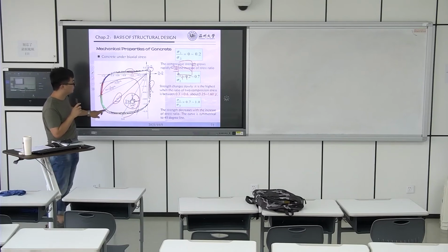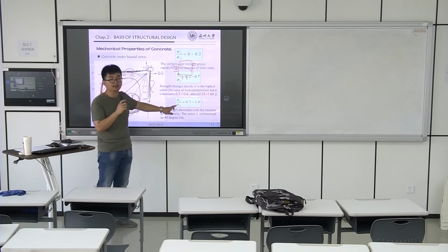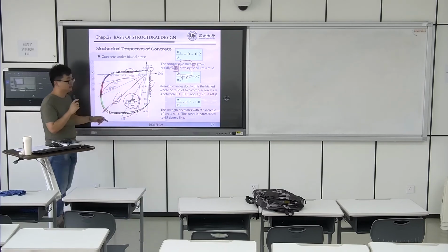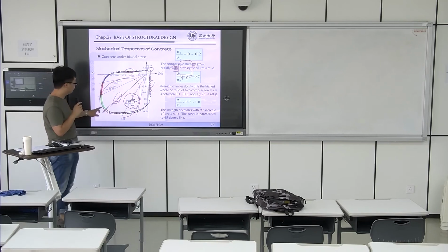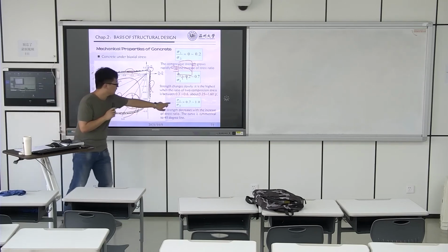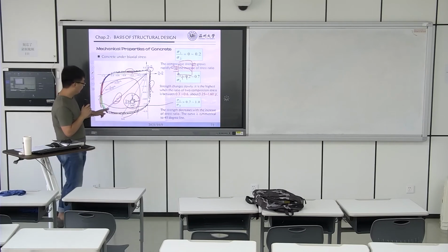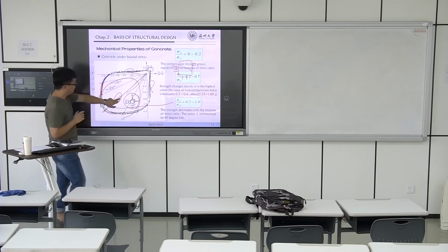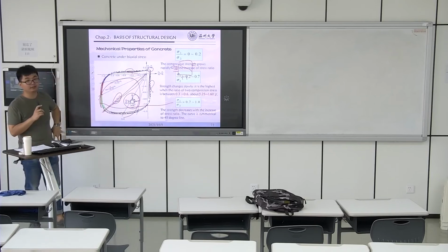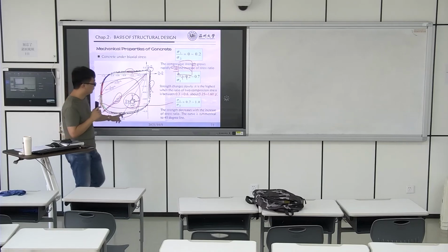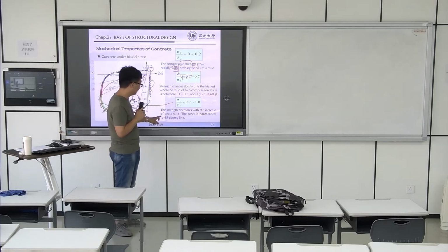In this period, sigma 1 divided by sigma 2, the value is in a range at 0.7. This period corresponds to this formula. And because this curve means sigma 1 equals sigma 2, during this period the strength decreases with the increase of the stress ratio.